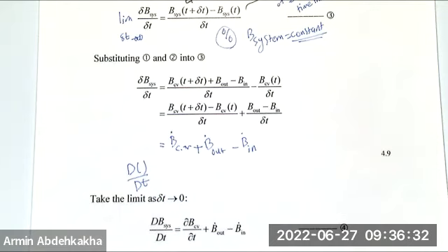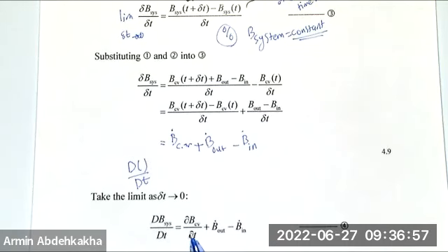So the capital D is for Lagrangian form, and the lowercase d, or the round one, is for the Eulerian approach, or local rate, right? We had two terms, the convective one and the local one. The local is going to be shown by the round d, but the capital is for Lagrangian. That's why we use capital D here, because the system is a Lagrangian system, a Lagrangian approach. So the time derivative change of that is going to be shown by capital D, right?